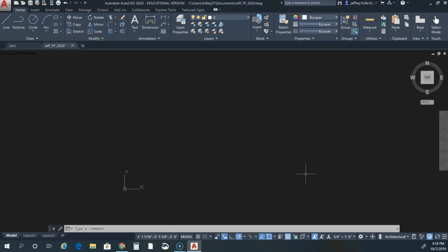We also want to look at our snap selections. Snap is something you've probably never heard of before unless you've used some drawing software. But our snaps, they're right down here, right across the bottom of this status bar. And snap cursor to 2D reference points is on. That's what you need to make sure is turned on. If it's just black like this, then you'll want to click on it to turn it on.